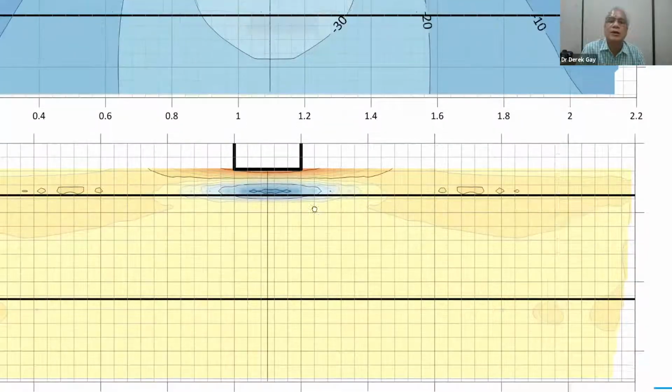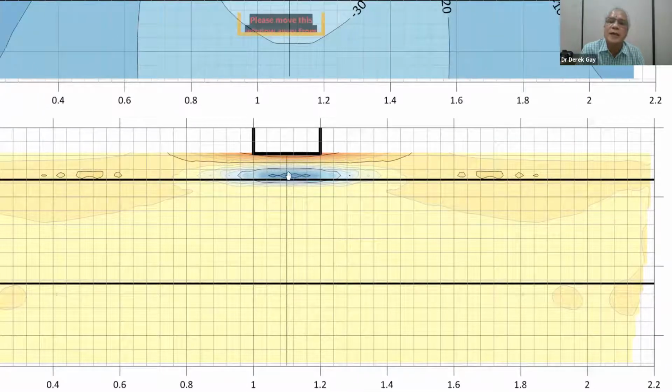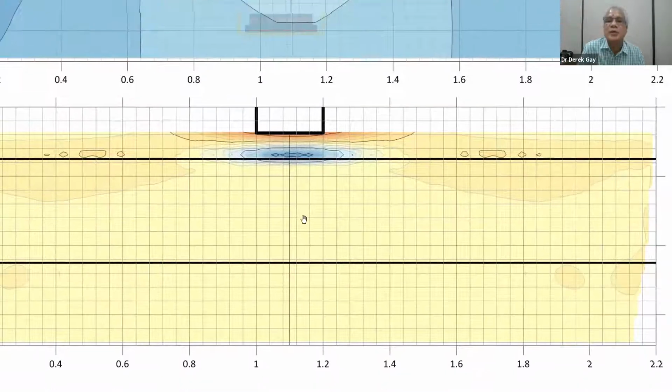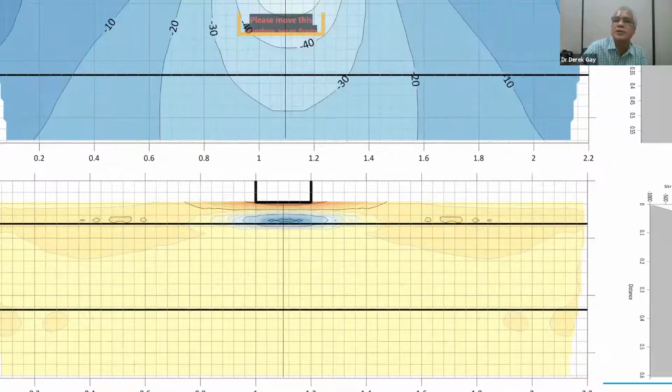When you look at the horizontal stresses, this is what causes the problem here. You see these horizontal stresses here are right at the interface of the asphaltic concrete and the base course, because there's almost a sharp drop in stiffness across this. It's like a step function between asphalt and base. And this type of stress-strain situation occurs at that interface. Again, when the asphalt begins to age or fail, we will see how that affects how the deformation is affected.